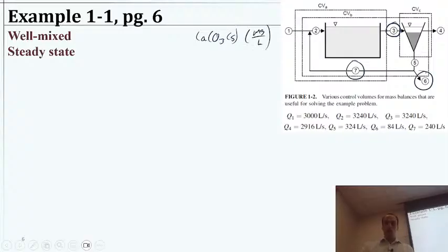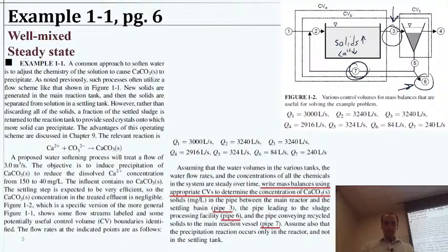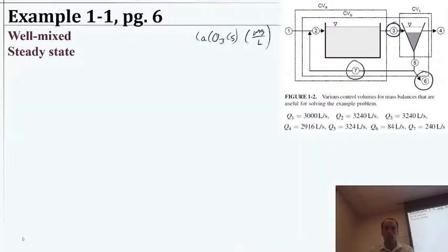And each of these locations, given this situation. The other thing we probably need to know, I think this part is given, but we need to reduce the calcium concentration, Ca2+, from 150 to 40 milligrams per liter. So we can say, in the input, Ca is 150 milligrams per liter, and the output here is 40, so Ca is 40 milligrams per liter there.